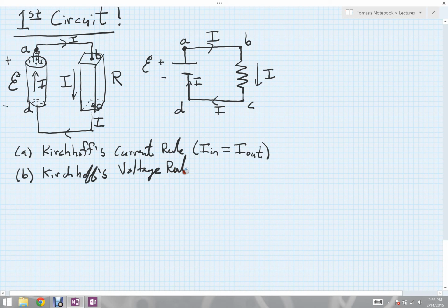Now this voltage rule comes down to, in the end, just this property of path independence that we've been talking about for voltages and for work, right, that we've been talking about from the beginning of this lecture. And what it says basically is that I can take any two paths, and the voltage to go around those paths will be independent of the particular path I chose. So there's a particular path that I'd like to choose. It might seem a little silly, but I'd like to consider the voltage going from point A to point A.